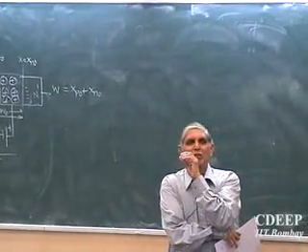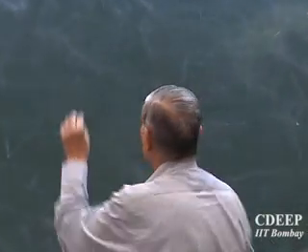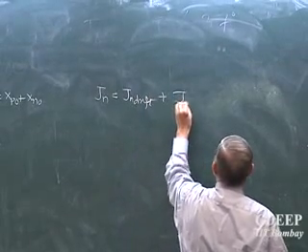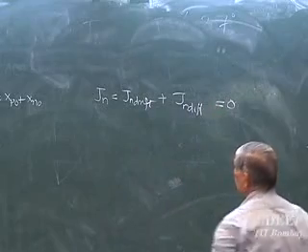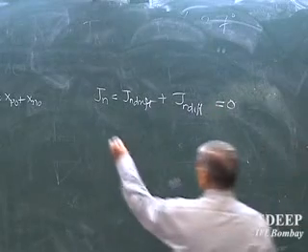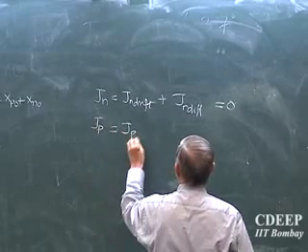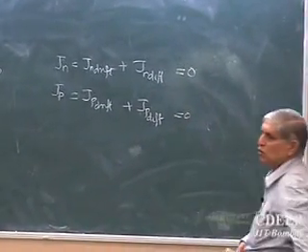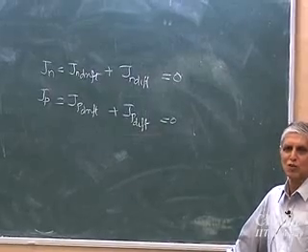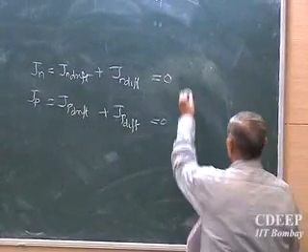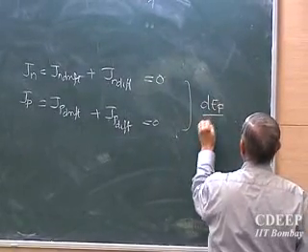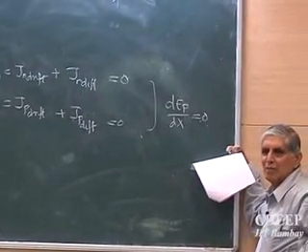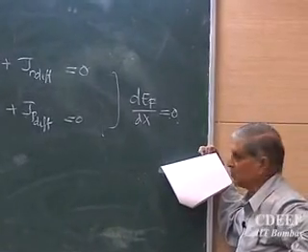Okay, we have already seen the other day, if there is no current, Jn for example, Jn drift plus Jn diffusion is equal to 0. Let's say the same for P. Maybe you can write Jp is Jp drift plus Jp diffusion is 0, because J is equal to Jn plus Jp is also 0, no current. Okay. Then we said that, just now I said, equilibrium, no bias, nothing happens, terminal constant, no currents.